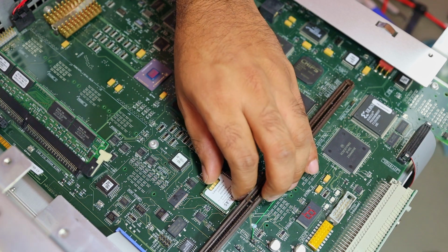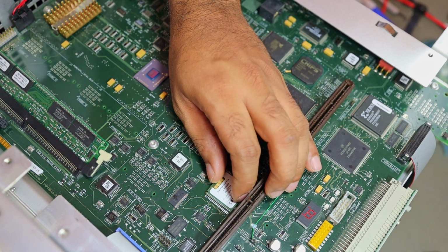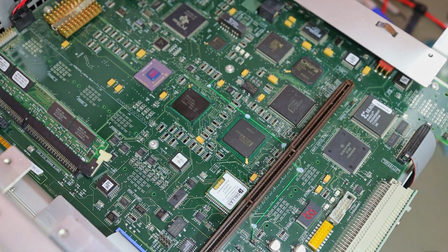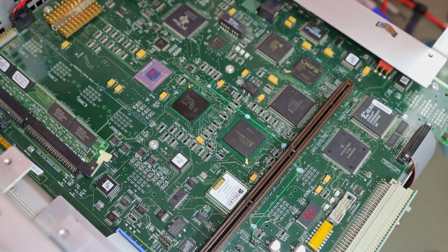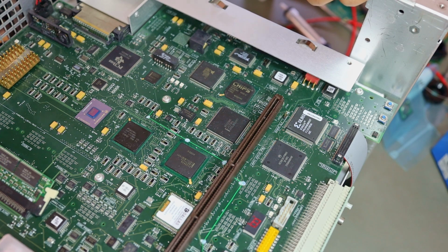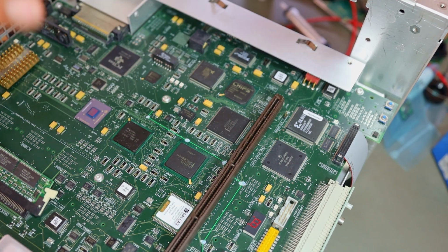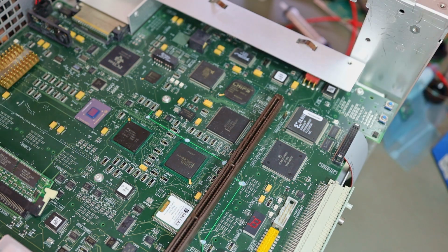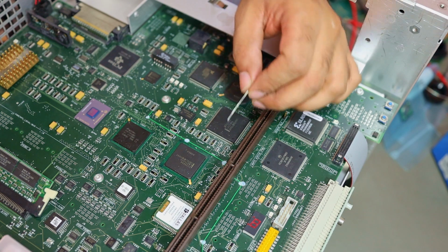Orientation is exactly the same as before. Maybe I need to inspect it a bit because I don't see the pads properly, how they are aligned, whether they are good or bad, or what is wrong with them. Soldering is somewhat hard because of the overhangs. The PCB is hanging over the pins, and you cannot clearly see if you have soldered them or not. I'll try one more time.